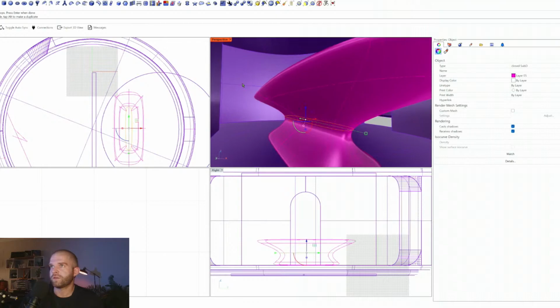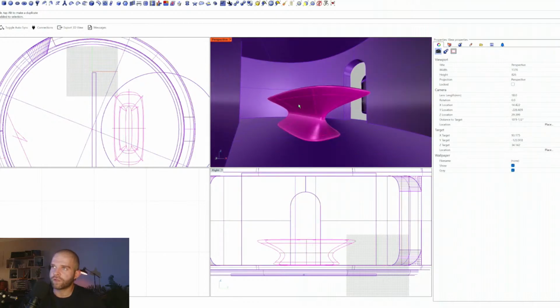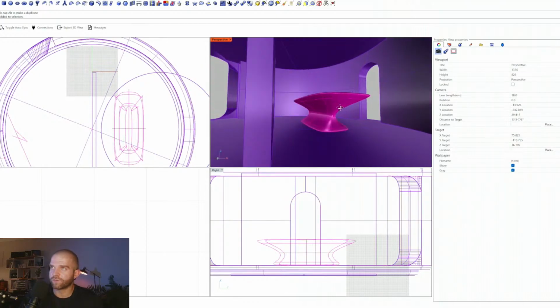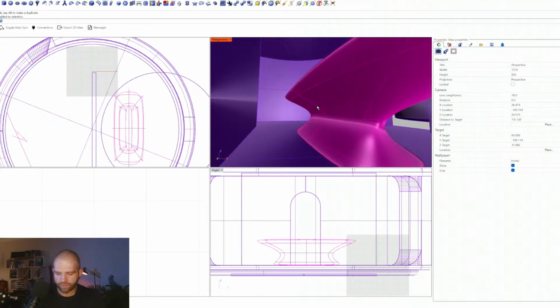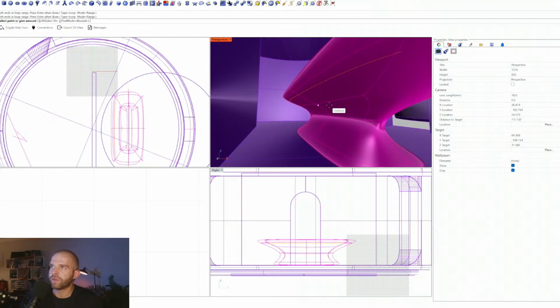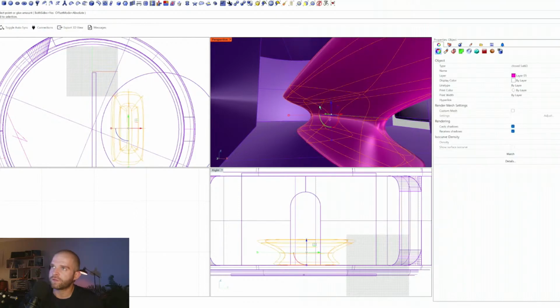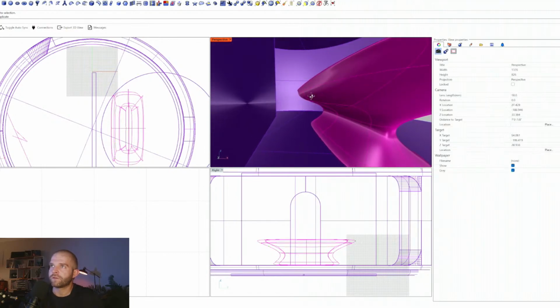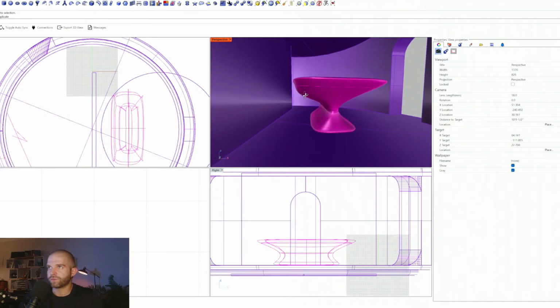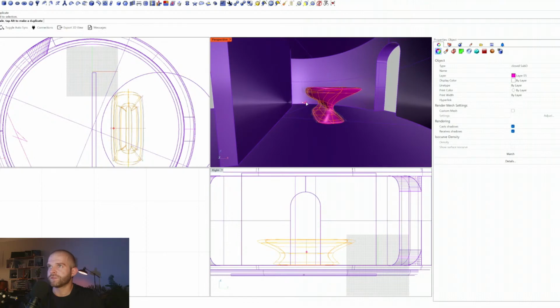and I could possibly add a drawer in there or something, but only to this side. So over to insert edge for here and here, move that halfway, and then select these two edges again and just pull these two forward. All right. So yeah, that has more space for a drawer on this side. I'll just make the whole thing thinner.